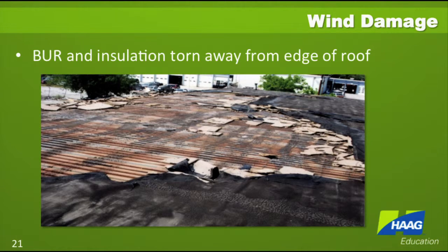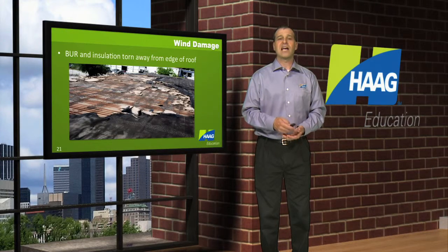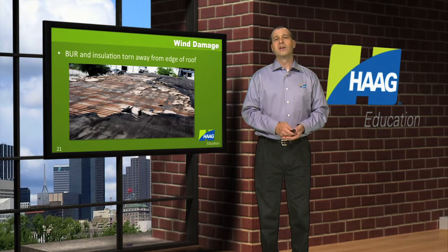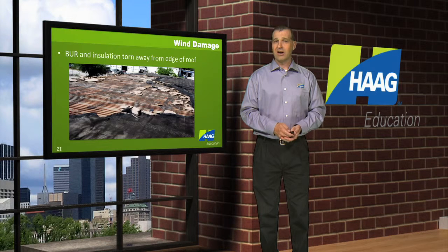In this photograph, we do have roofing and insulation boards that were removed starting at the edge of the building on the left side of the photograph. Now that the roof is open, moisture can get underneath that roof decking, and you've got to verify just how far the moisture has gone, how much wet insulation you have, and what the damaged areas of the roof are relative to the size of that roof or roof section to determine whether a repair is feasible.